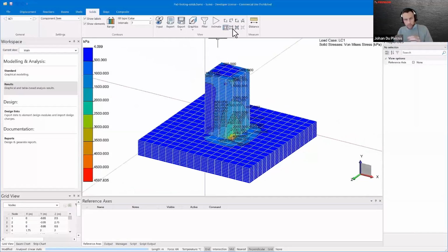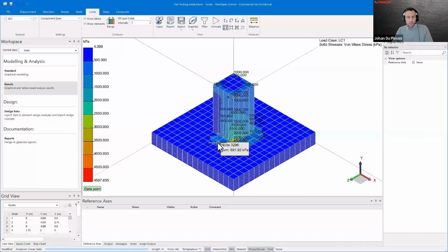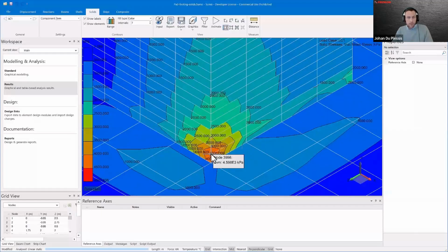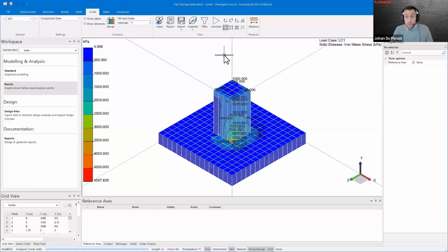We can see on that corner where the stress is at a maximum, we've got the von Mises stress. If we zoom in a little bit, we can see at that node it's about 4.5, or let's round it off to 4.6 megapascals of von Mises stress. That we see at that corner of the base, and that's obviously the most stressed point. So, not a very interesting one.